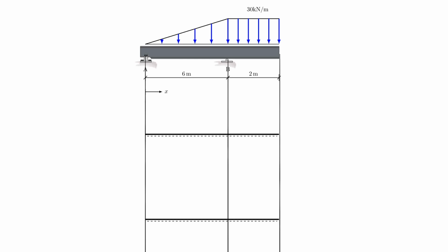Let's start with the shear force on the top, V in kilonewton. And I will now include the values that I know, and I will develop this without really calculating the functions. But of course, your job is to verify my functions or my values through your functions. But I know that I have to start at 0 here, and that I have to have a jump which is equivalent to the support reaction, which is equal to plus 20. So I need to have a value of plus 20 here.